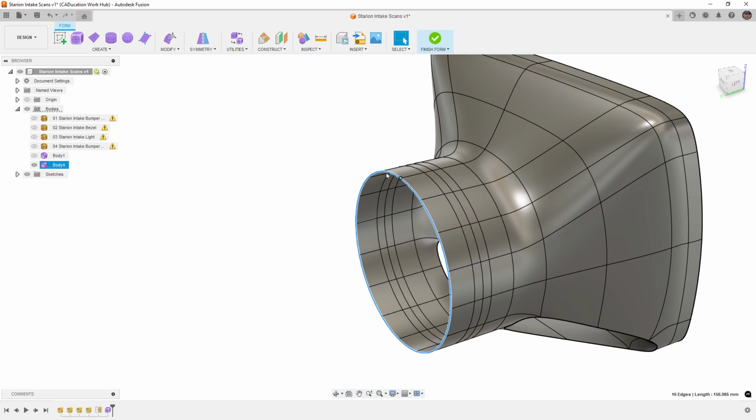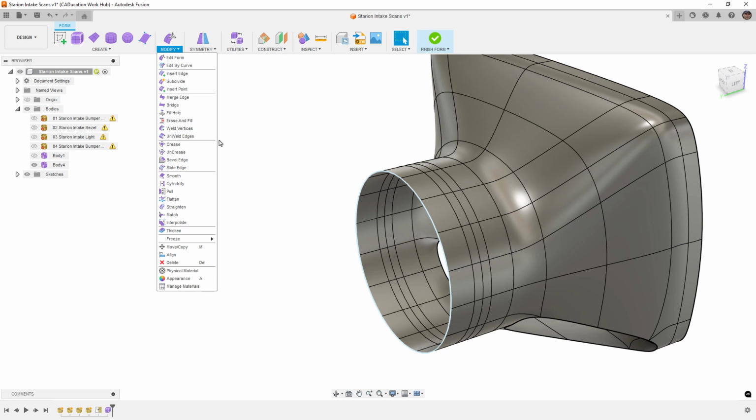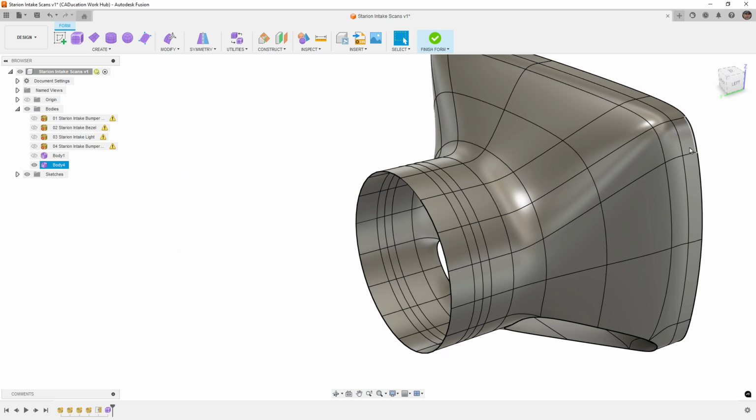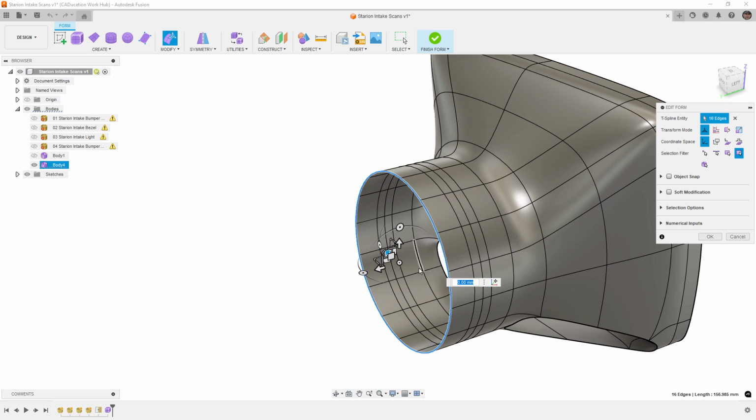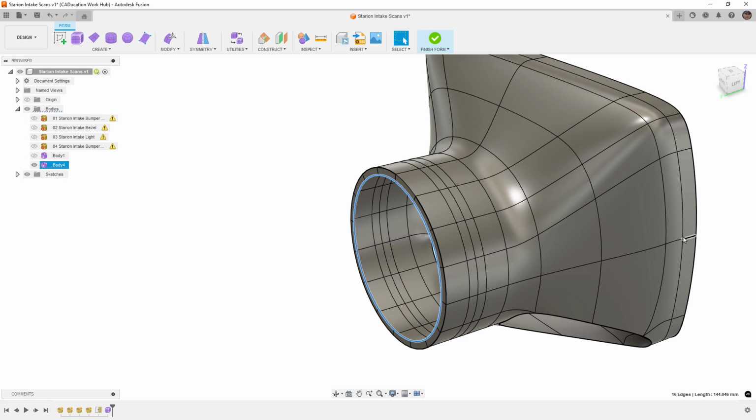Another thing that you can do to preserve that is if we try to extrude from that edge, and I'll just show you here. This is something I do from time to time as a temporary solution. So we're going to take that edge, we're going to hold down Alt and Control, and we're going to scale it inward or outward and say okay.